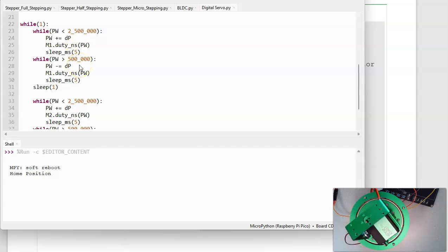back to 0.5. So the second motor is actually a 180 degree motor. The second one also sees a 180 degree motor. That's a digital servo motor. By setting the pulse width, I can control the angle. It's actually got some pretty good torque. The torque is due to all that gear reduction.